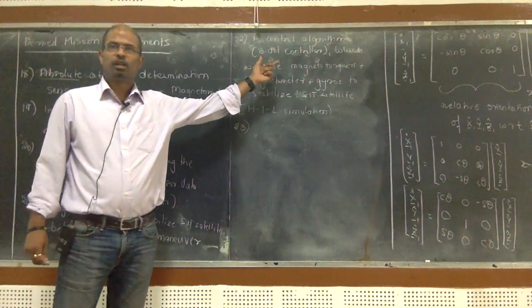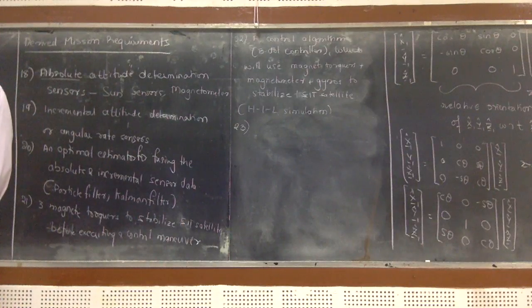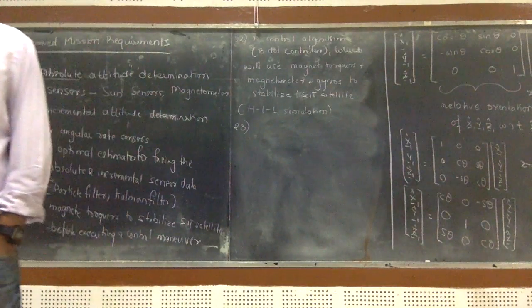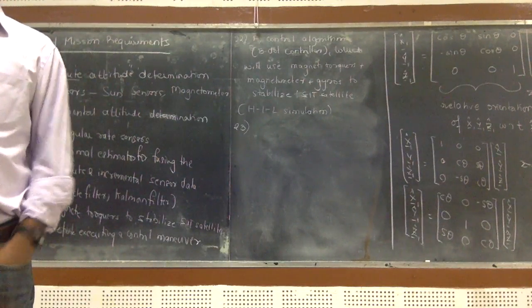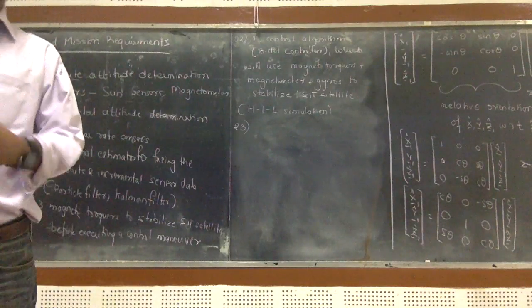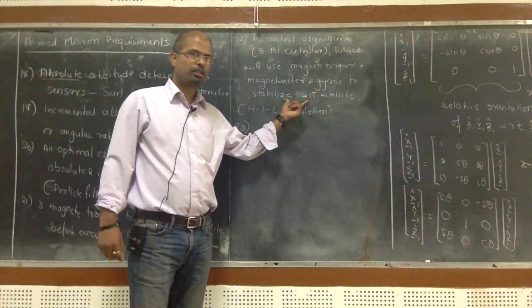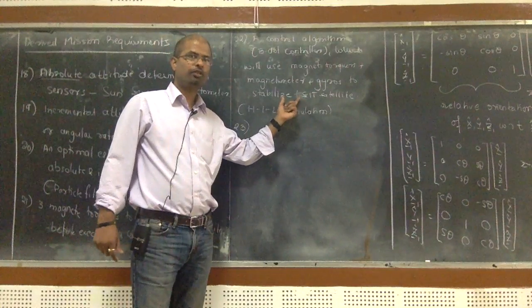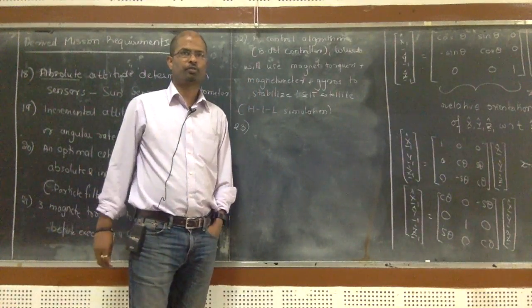Is this clear? How you're doing control here? Is it clear, you guys? It's okay? Stabilization is not at all concerned with attitude. No, exactly. So you don't worry about where it is pointing. You're only worried about stabilizing. So here the goal is to bring the angular rate down; the desired angular rate is 0. That is what your goal is. So you're not really worried about where it is pointing.